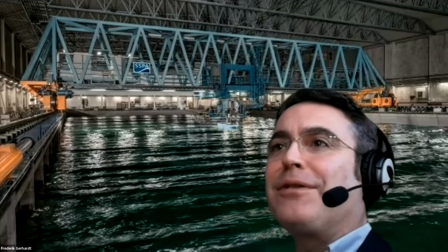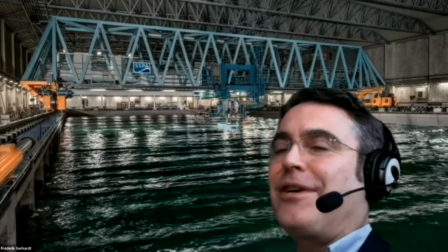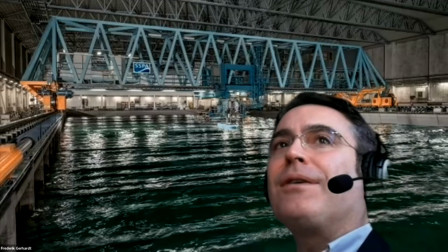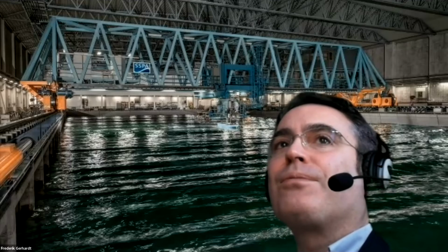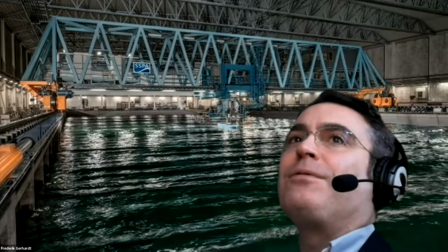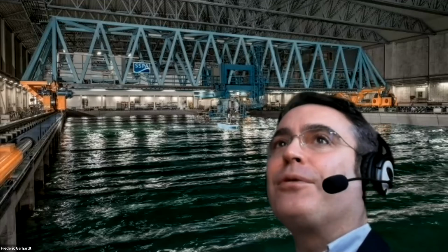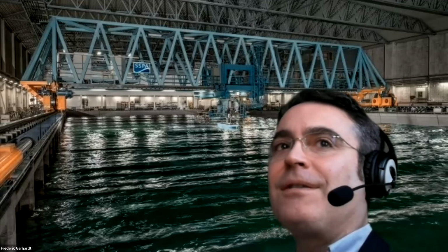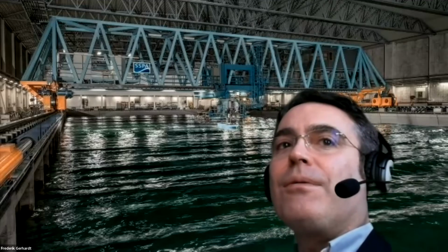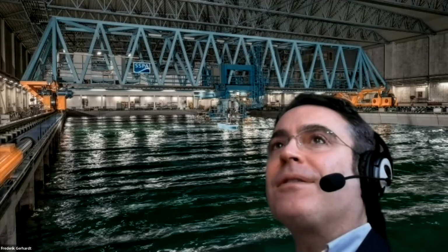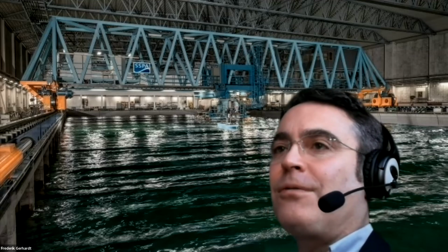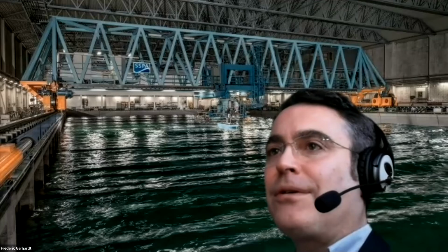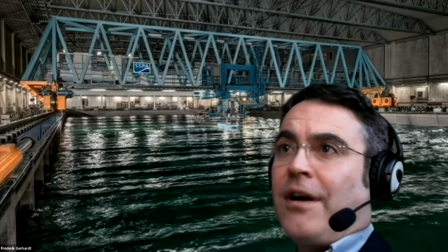Yes, and to be honest, of course, there's something missing, and we've done those sea trials in the WASP project, and we figured out that the interaction between multiple propulsive devices, between sails and the hull, is probably a much bigger issue than we expected initially. So if you stick two sails on a ship, you cannot just say propulsive force is 2 times sail force at this particular angle and wind speed. There's stuff going on which we still don't fully understand, or well, we understand it, but there's still ongoing research on how to model this, and this is the big advantage of having such sea trials or experiments, that you can validate your models and see how good they are. Joshua.